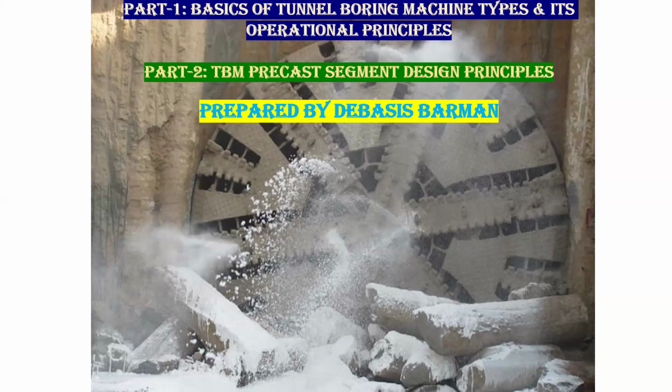In NATM or conventional tunneling, we first install the primary support to stabilize the excavation or the opening. Once the opening is stabilized, we install the final support that is going to take the loads for the next 100 years of the design life. So TBM tunneling is a more advanced process of excavation, of support installation, and also in terms of waterproofing and other things. If you talk about serviceability or durability, everything is very advanced.